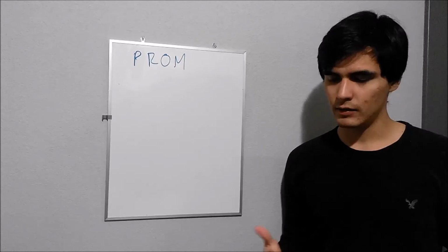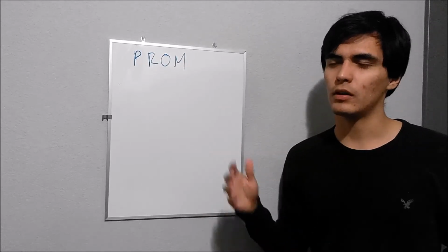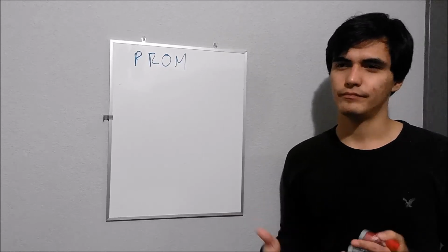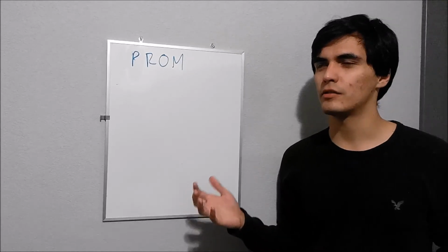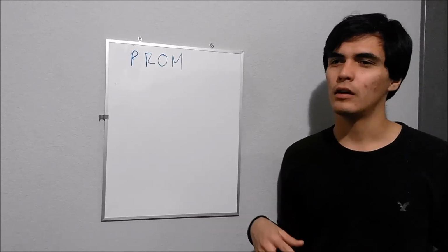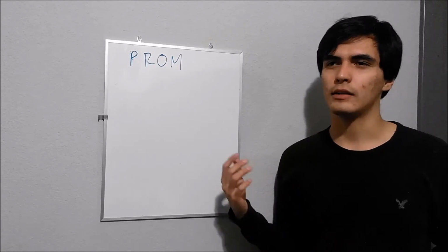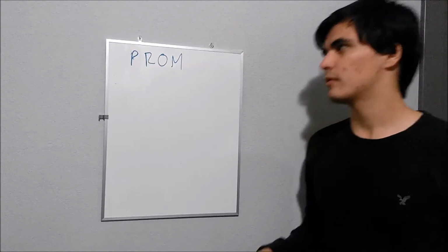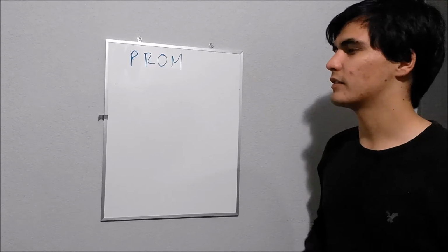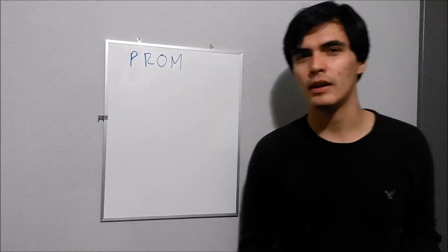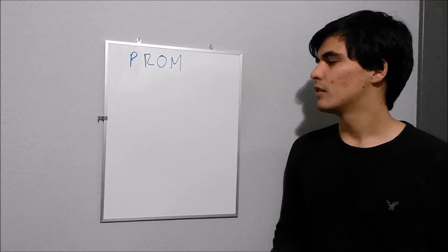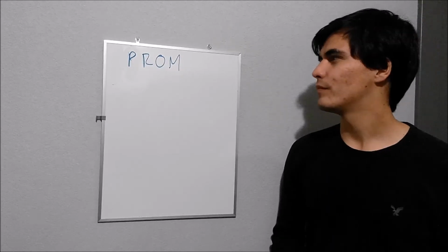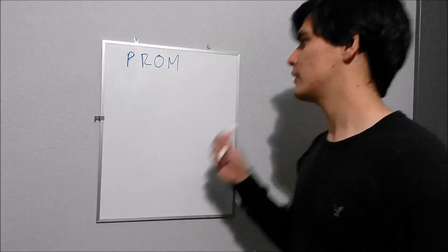So you can make a program, and with that program you can choose which fuses you are blowing of the AND array that the PLD has in the inputs. And you can just program it once. It's not like the other memories that we can program all the times we want. So you need to think it through well before you program the PLD.